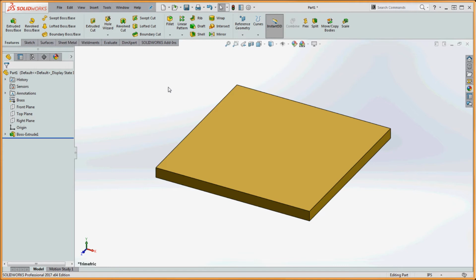But one thing I've noticed with SolidWorks, if you put your model together correctly with a lot of good sketch geometry, you don't have a lot of redundancy in there and things that SolidWorks could get tripped up on. It's a really stable program, and sometimes it's real easy to get casual about it and not save your part. But do it, save it often. It's just really good practice.